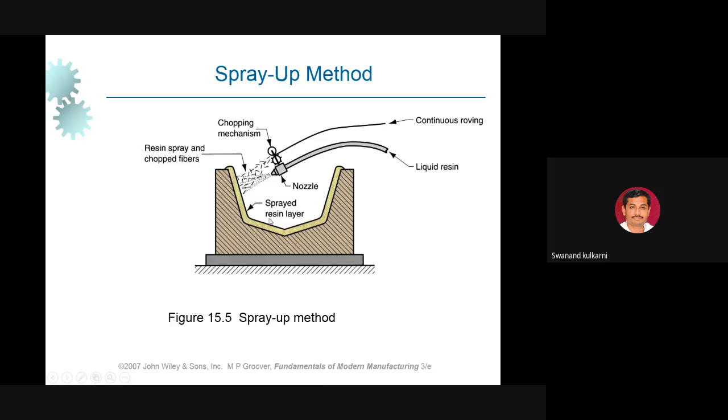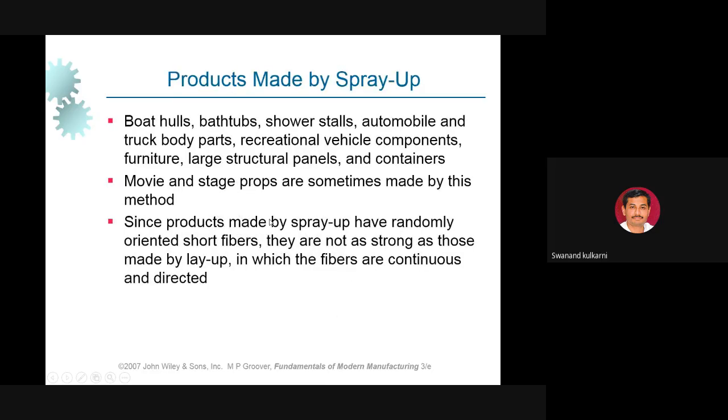Is it okay? So hand layup technique and spray up method. Now, with the help of this spray up technique, what is manufactured? Boat hulls, bathtubs, shower stalls, automobiles, truck body parts, recreational vehicle components, furniture, large structural panels, containers, different stage and setup preparation.